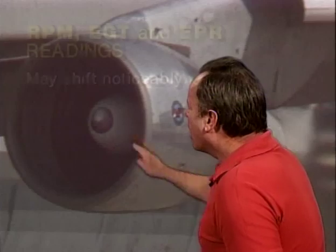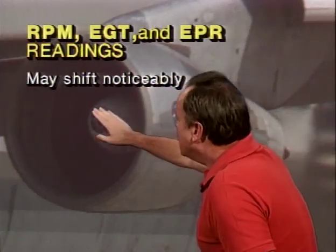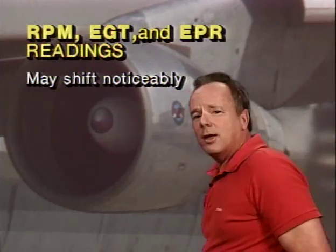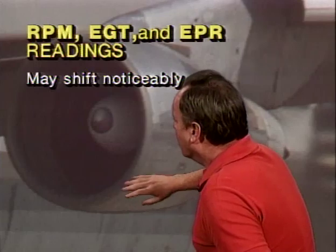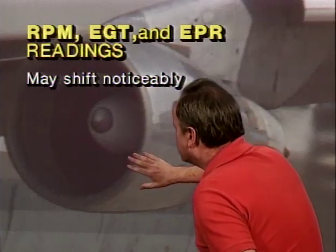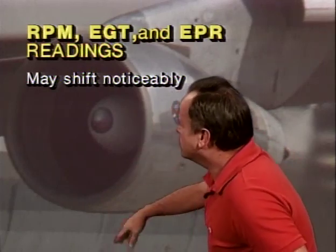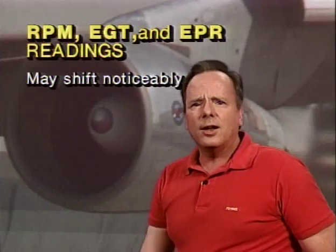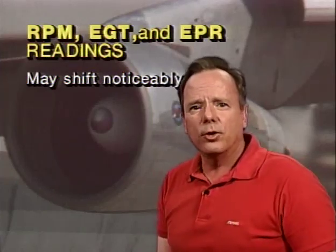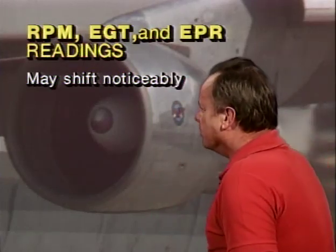For instance, your RPM, your exhaust gas temperature, and EPR readings may shift noticeably because you're taking bleed air away from that engine, which the engine normally uses to run the compressor, and you're applying heat to the inlet of the engine, so you're going to get some changes in RPM, EGT, and EPR. You might not notice too much change in the fuel flow, but you will in these parameters: RPM, EGT, and EPR.